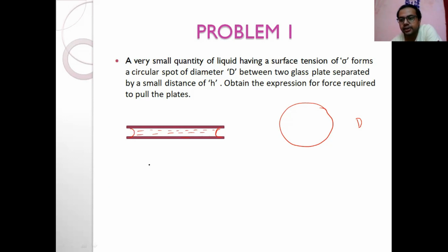So here the surface tension force is acting, pressure force is acting. Here the pressure is Pi, and here the pressure is Pa, the outside pressure. Now, concept-wise, this Pa should be greater than the Pi. That's why it is holding the two plates. But we are thinking about the delta P, the differential pressure, how much it is here.